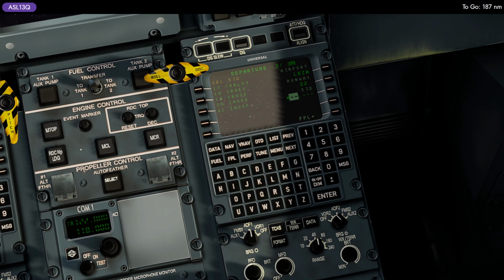The way I do it, I select this one, so it is this one, and then we can see that it is straight ahead on course 223, then left turn 2 miles from Lima Uniform Kilo and the VOR, and then we are actually going to the left on the 0901 course from the Papa India Sierra VOR until we reach this point here, where we are actually going on 069 and leaving over Victor Bravo Alpha VOR.